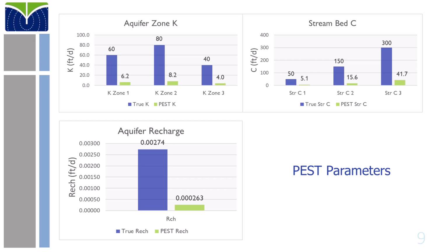The problem here is, as is well recognized in the literature, that hydraulic conductivity and recharge are highly correlated. What PEST has done here is start with low values of aquifer hydraulic conductivity and streambed conductance. And it found that for any reasonable value of aquifer recharge, the heads were way too high. So it just kept reducing recharge until the head values fell to calibration levels, and then it stopped. This created a situation where both recharge and conductivity, or conductance values, were 10 times too low, but the heads